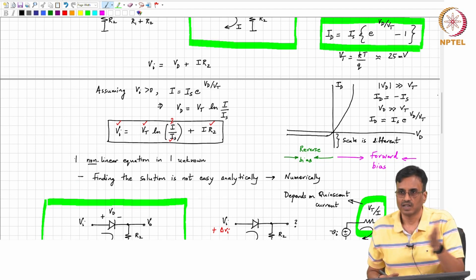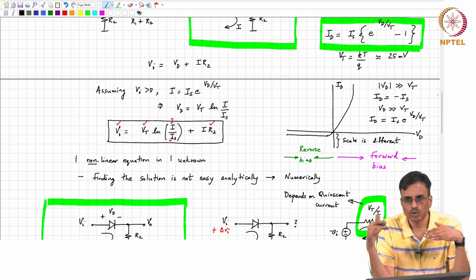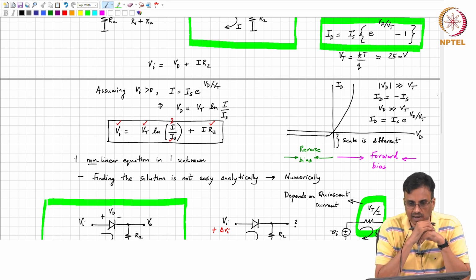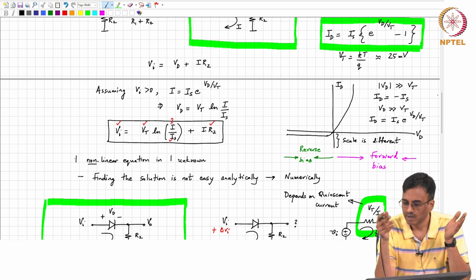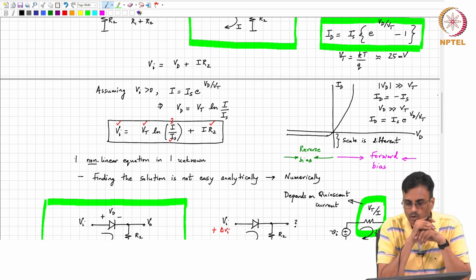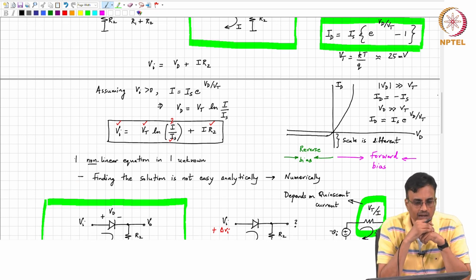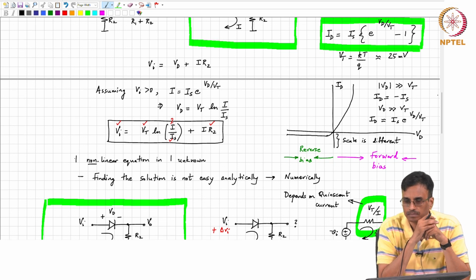So a large change in the applied voltage is expected to result in a linear change in current, with a proportionality constant close to 0. Whereas in the forward bias region, it is exponential. So to evaluate what constitutes a small signal, we have to find the higher order terms of the Taylor series, compare them with the first order term.